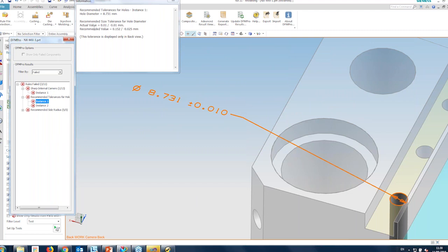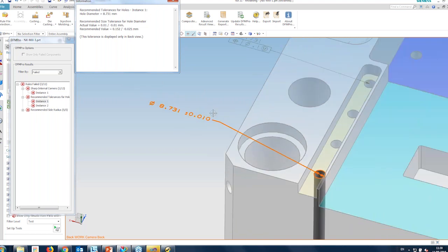Another thing, if you see on this machine component, you have some tolerances which are added to some of the holes on this particular design. Now, many organizations, especially the aerospace and defense customers, what we have seen is they're moving towards the MBD initiative, that is model-based enterprise. What they're trying to do is get rid of drawings and have the 3D as their master. So in that case, you will slowly have to add tolerance information for all the features on your 3D part, which will be consumed downstream by manufacturing teams.